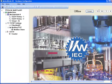And so by using this hardware configuration utility within Pro, you can further tweak your system so that the critical I/O are synchronized with a fast task and your non-critical I/O run in a slow task. The idea is, why spend processor time updating and writing the I/O that doesn't really need to be updated that often? So the servo pack has an I/O.